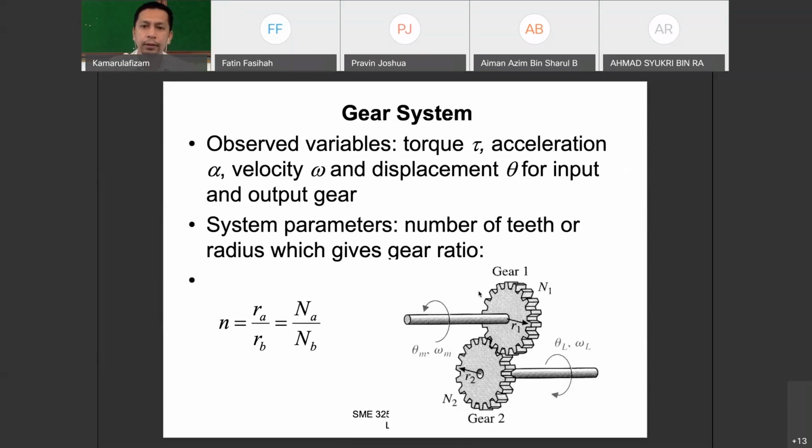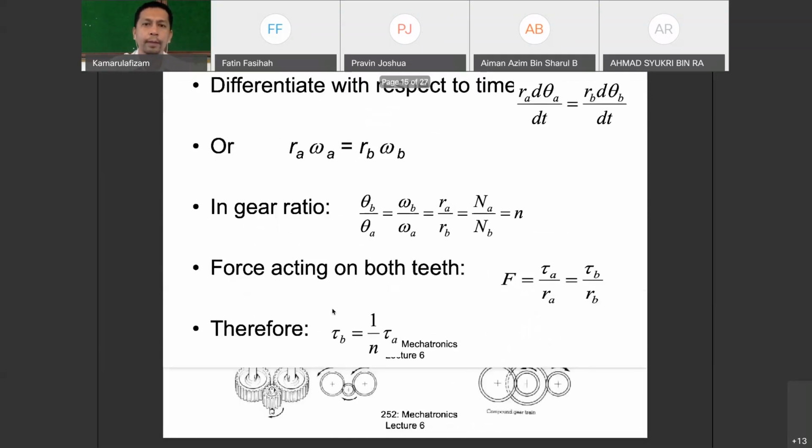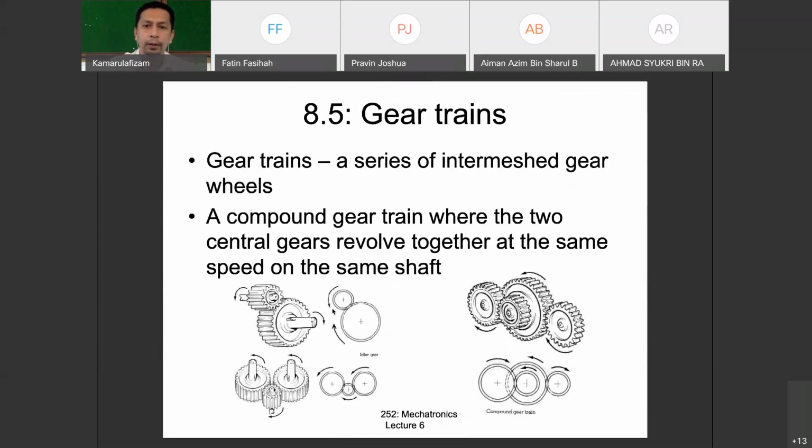That's the thing. Alright, RPM, angular velocity and torque. Kita nak tahu kalau kita with this design, kalau kita bagi 10 Newton of torque, berapa yang akan keluar on the other side. Alright, sebab gear again bukan saja dia transfer rotation RPM, input and output, by the ratio, dia juga transfer kita punya torque, and this is how you get the torque lah.